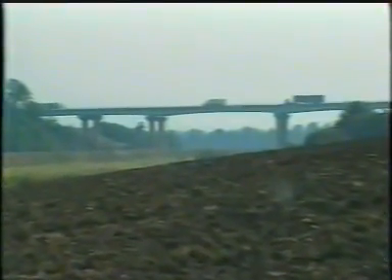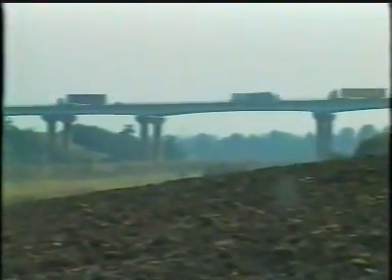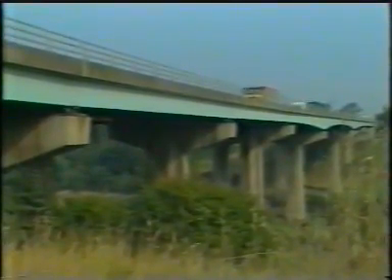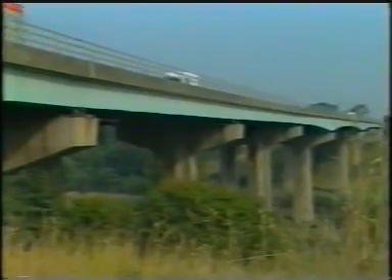In this building, the floor slabs are supported on shelf angles, a form of construction which provides good restraint. Similar considerations apply to bridge construction. Here, the longitudinal beams may be restrained on their upper surfaces. It is important to remember that, with a continuous beam supporting a floor slab or bridge deck, the slab will provide restraint in that region of the beam which is subject to a sagging moment. But, adjacent to the reactions, there will be regions subjected to hogging moments, where the lower flange is in compression, and bracing of this flange, too, may be necessary.